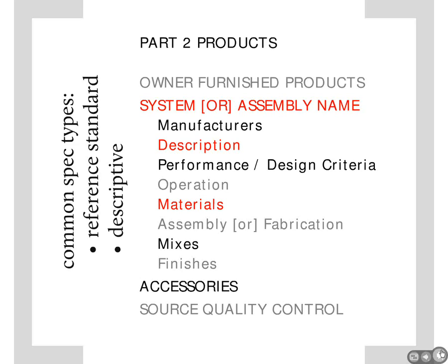Now, if we're talking about sealants for the soft joints, the control joints that you have to do in masonry, that to me can be an accessory. Weep vents? Potentially. I sometimes most often specify those with the flashings because they're so integral with the flashings, but they could be an accessory. Yeah. So it's kind of the miscellaneous bits and pieces that are needed to supplement the primary products. Correct. But I would never try to put any of the primary products into an accessory function.